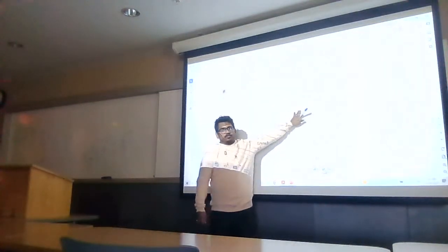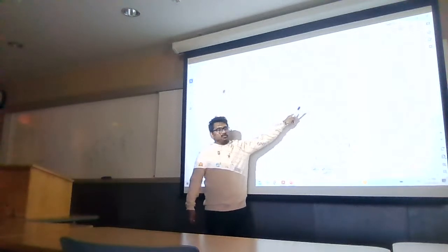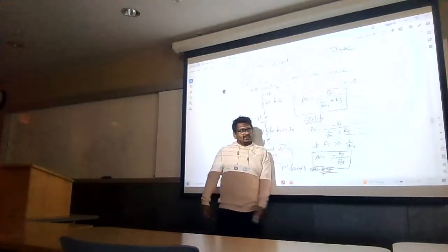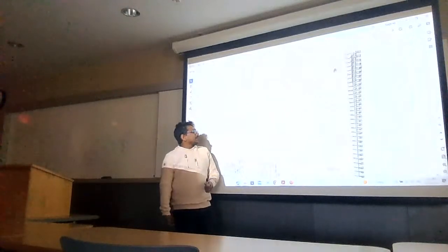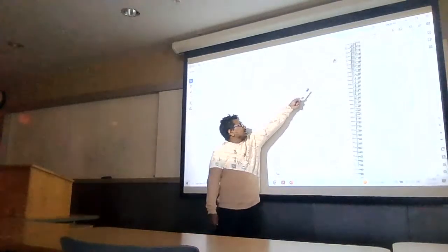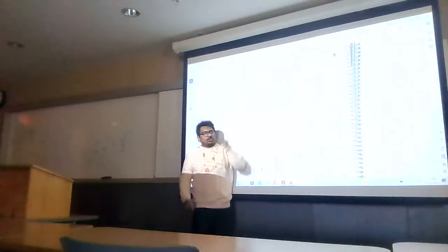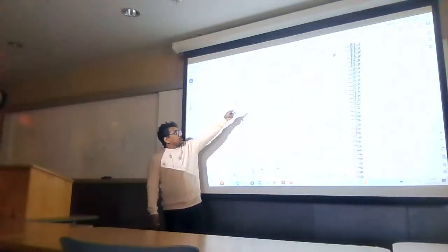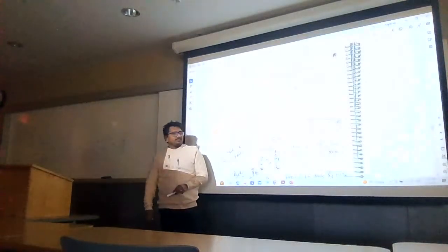It's a general formula, and you have to remember this formula. This is minus RD divided by 1 by GM1 plus RS. If you remember this one, then, okay, RD. But here, what is RD? RD means the resistance of this one. And as I claimed, the output resistance of a diode connected device is 1 by GM2. So I can replace RD with 1 by GM2 and everything is the same.